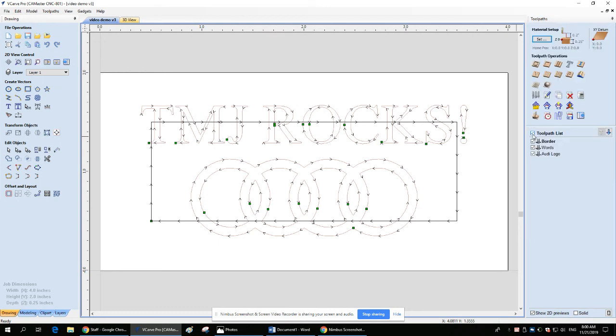It would be a courtesy to everyone in the class. When you're finished with your final designs, try to check, I think I said in the assignment, maximum cut time about 8 to 10 minutes. We can't have people on the machine running for half an hour while they do some crazy design with thousands and thousands of little vectors everywhere. It just isn't fair to everyone to get a chance on the machine. So, as a courtesy, when you're done, before you post process, double check your cut time. Make sure that you're not going to hog up the machine on everyone.